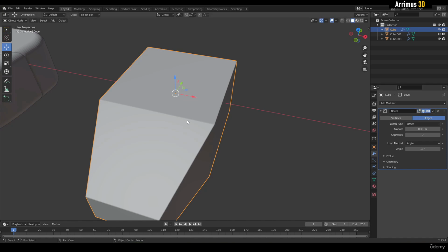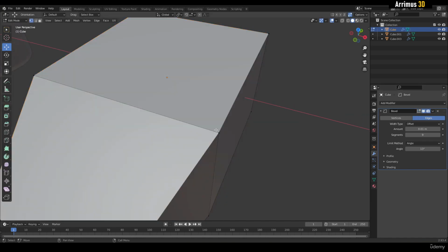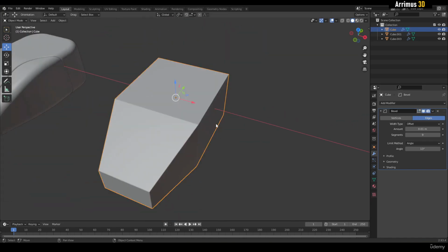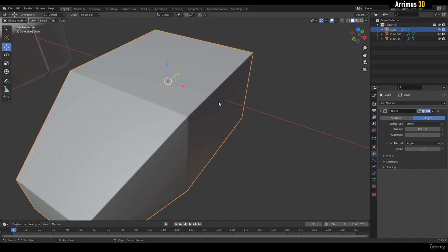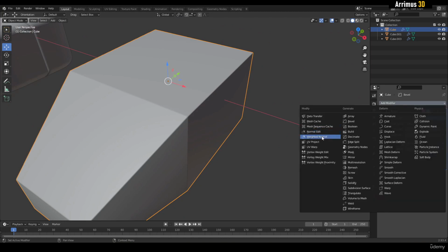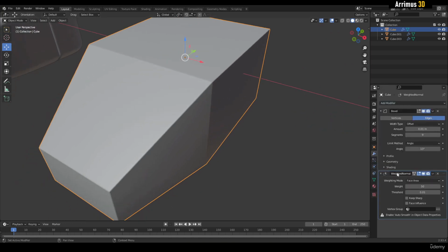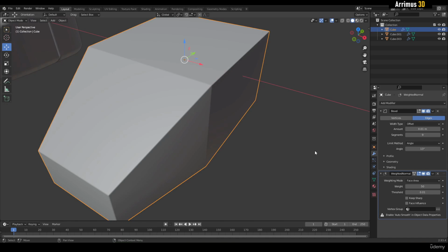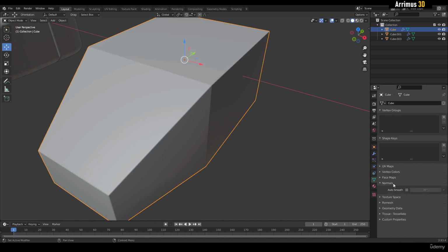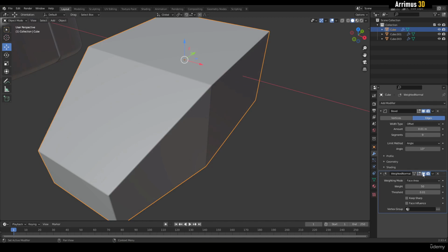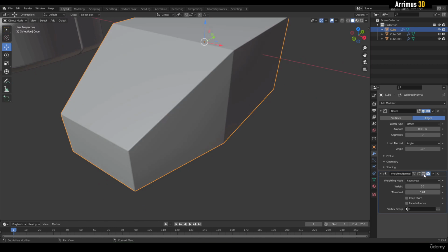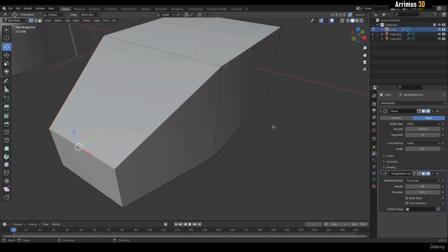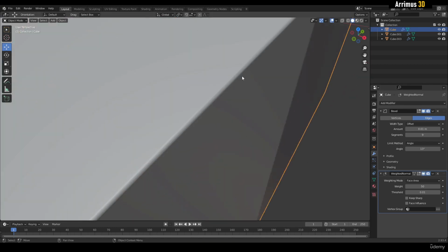So it's making it look a little bit better, because of what the bevel does here, especially if we shade smooth and perhaps apply weighted normals on top and use normals here as well. You can see how that modifier really improves the flat surfaces. So the bevel modifier is doing some good things.